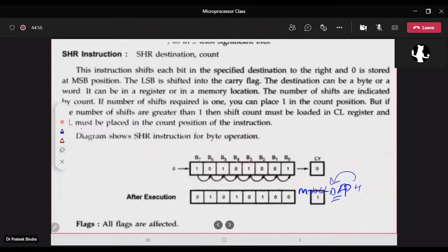So next we have SHR. Please, it's not the same as the SHL. It's not just the opposite of that, so people make a lot of mistakes here. So please see this carefully. Although it is just the opposite of that, you can see this figure. What I have now done is, smartly, I have put my carry flag, which was there in the last example, in this location.